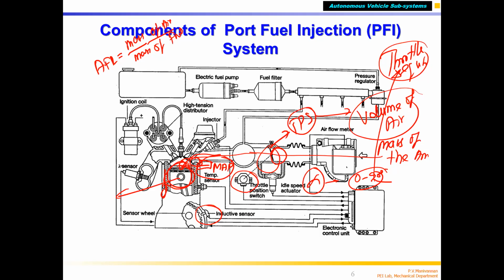But it is an open loop control. Correct? The N alpha method is also open loop control. No feedback is given. You are not measuring air fuel ratio. Correct? Your lookup table map says that if I run the throttle at this opening, this much engine speed, and inject this much quantity of fuel, the air fuel ratio is, for example, stoichiometric. That you calibrated in laboratory condition, 30 degrees, 1 bar. But if temperature changes, the table is invalid. Correct?